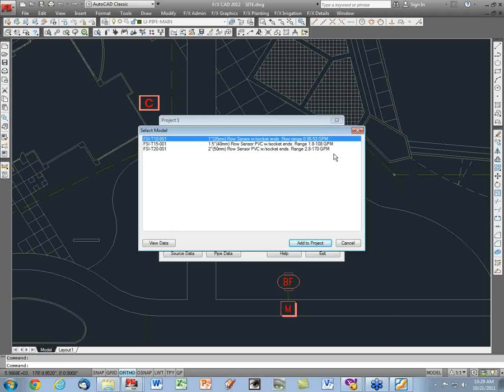And very importantly, the corresponding flow range that they're capable of. And notice that they go pretty far down. The 1 inch goes down to 0.86 GPM and up to 52, and then it's 1.8 to 108, and 2.8 to 170, because we get a lot of situations where we have drip, and sometimes those drip can be down to even below 3 GPM on one valve. So we have to be careful about what the minimum is, as Norm said, and there's the maximum.